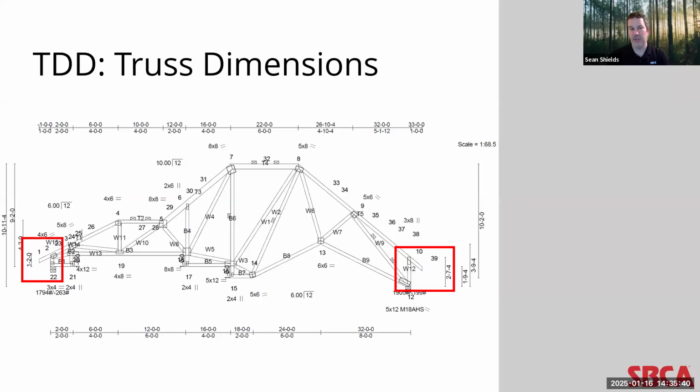and then the elevations change, sometimes it can be difficult to ensure that all of the trusses have, for example, the same roof diaphragm height, which would be a real problem in the field if they aren't, right? The roof sheathing won't go on correctly. So again, building designers can help by specifying what they desire to have happen out on their plans.